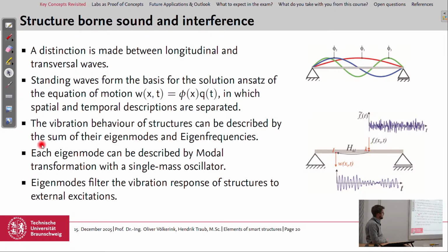And by modal transformation, we can describe each eigenmode by a single mass oscillator and sum them up to model the overall behavior of the structure. Also, eigenmodes act as a filter on the vibration response. So even if we have a broadband signal exciting or disturbing the structure, not all eigenmodes are excited.